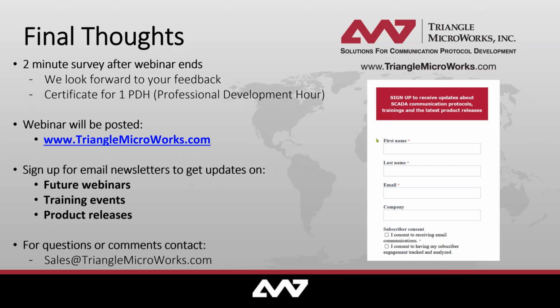We've done everything we can to make those links automatically, but in some cases, say your design uses GGIOs instead of the logical nodes defined in the standard to perform a specific function, you would need to come in and make those manually. That does take a little bit of time, but depending on the size of the substation, maybe an hour or two.